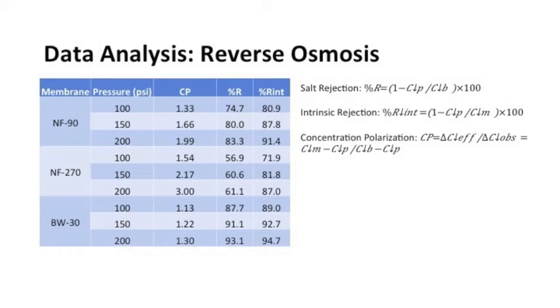The concentration polarization was also investigated. The concentration polarization of the membrane impacts the pressure required for the diffusion of water through the membrane to occur. Concentration at the membrane on the feed side of the membrane is larger than the observed concentration gradient. This is proportional with a larger osmotic pressure gradient needed to be overcome for the water flux to occur, meaning more power needs to be supplied to the pump to meet the pressure output.